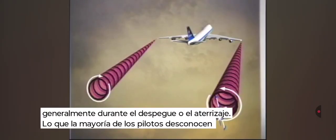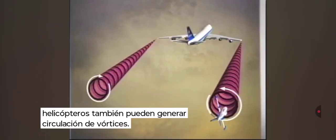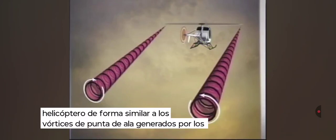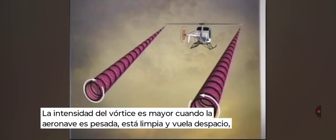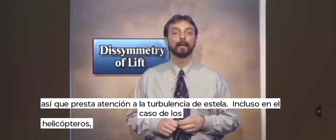What most pilots don't know is that helicopters can generate vortex circulation also. These vortices trail behind the helicopter in a manner similar to wingtip vortices generated by airplanes. The vortex strength is greatest when the aircraft is heavy, clean, and slow. So watch for wake turbulence even around helicopters.